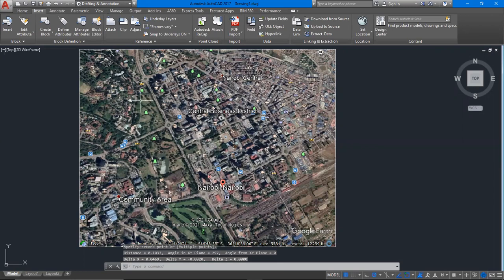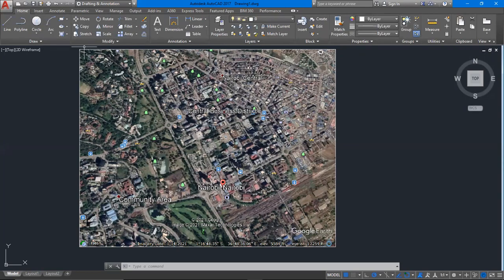So what I will do, I will change this image so that when I measure the distance from here to here, I can get 1374. I will use that as my reference line, because I know the distance from here to here. I will just use it as my reference line, and then it will scale the image, so that if I measure the distance at any other place, it can be as accurate as it is on the ground. That is where scaling with reference comes into application.